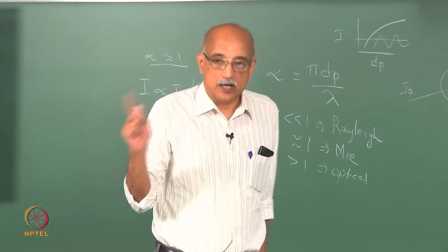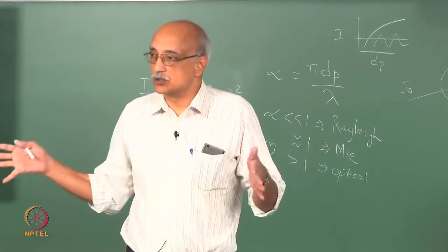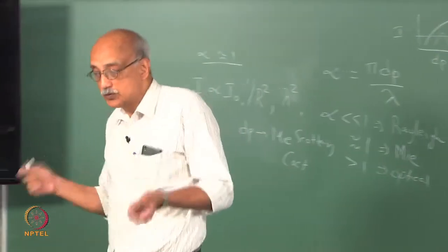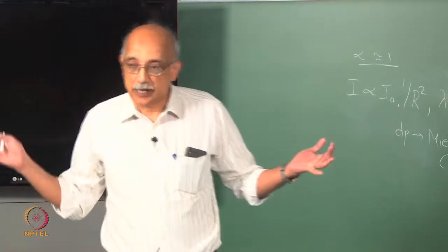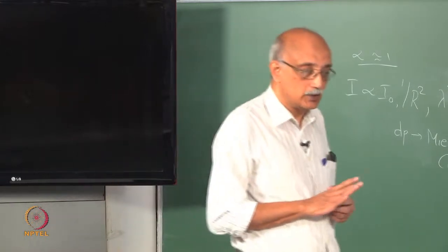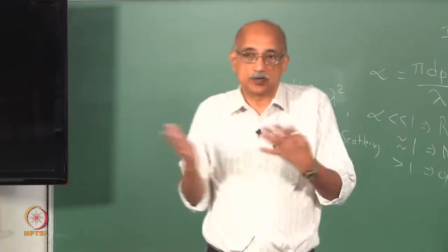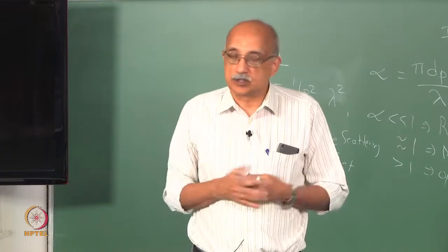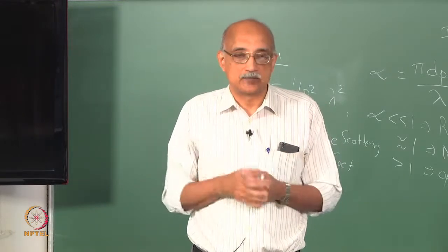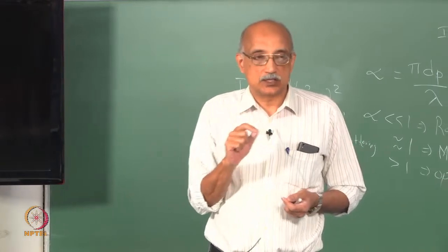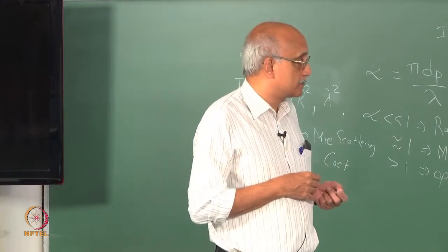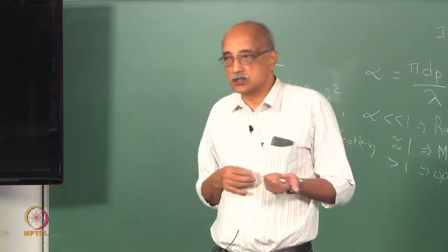D stands for dynamic range. That is basically the size range in which you are doing the measurement. The wider the size range, obviously the more useful the instrument is. You can take many different samples and run them through the same instrument, but there are many well constructed instruments that are really only good in a very narrow size range, could be from 0.1 nanometers to 10 nanometers. But as long as the instrument is doing its job well in that size range, that is okay. But you have to understand the size range in which the readings are reliable, and that is called the dynamic range of measurement.